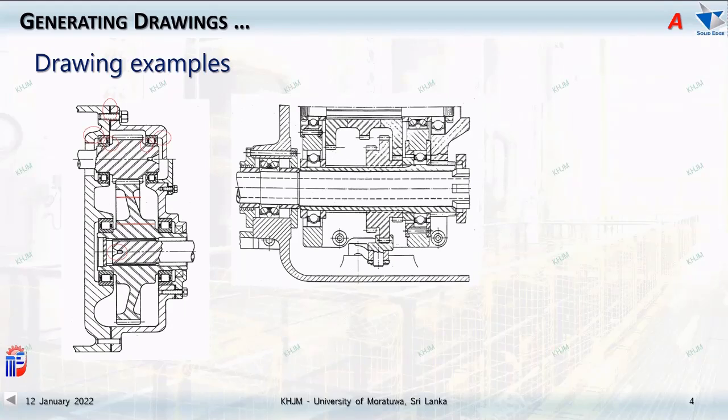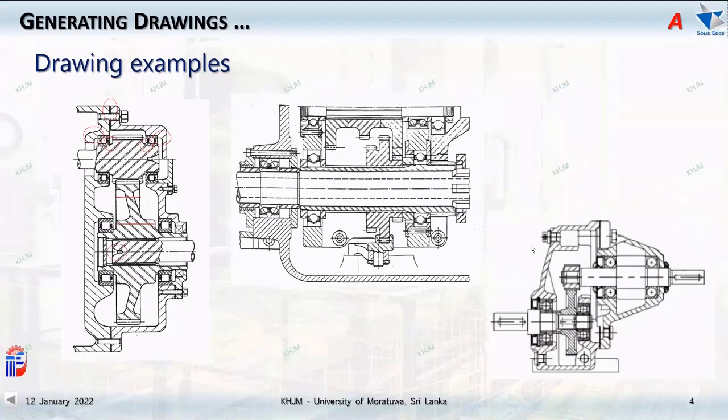They will not function. So I have given you these examples to see how these variations can be put into your drawing as well. So we have to consider them seriously: how the bearings are mounted, how the end caps are mounted, how the bush or whatever it is, and also some standards like how to produce gear wheels. Right? You can see this bearing over here on this side is slightly different from the bearing on the other side.